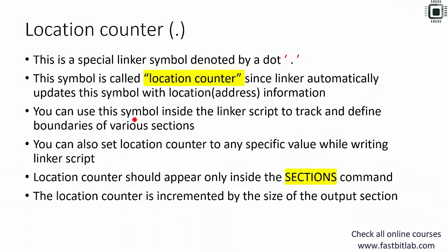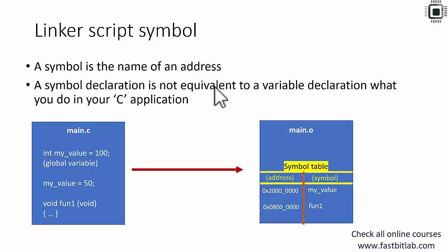Let's make use of location counter in our linker script. Before that, we have to explore one more thing, that is linker script symbols. Creating linker script symbols: we use location counter symbol with other linker script symbols. Let's explore the linker script symbol in the next lecture. In this lecture, let's understand linker script symbols, and later we can understand how to use the location counter and linker script symbols together.